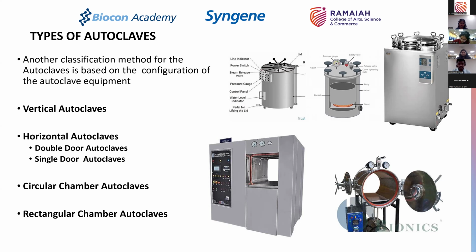Normally you attach a laminar airflow unit at the outlet, so the components coming out are protected and not directly in touch with the room air. So there is a cleaner, HEPA filtered air directly touching the sterilized product, thereby maintaining sterility. So if you are doing a sterile manufacturing operation, for example for injectable products, you would have to unload.